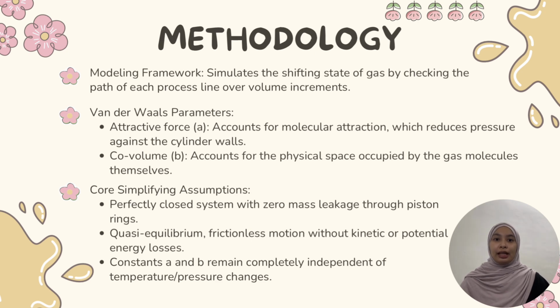To keep the underlying calculations stable, a few standard engineering assumptions were applied. The cylinder is treated as a perfectly closed system with zero mass leakage. The piston moves under frictionless, quasi-equilibrium conditions. Changes in kinetic or potential energy are considered negligible, and parameters A and B are treated as constants that don't fluctuate with temperature spikes.